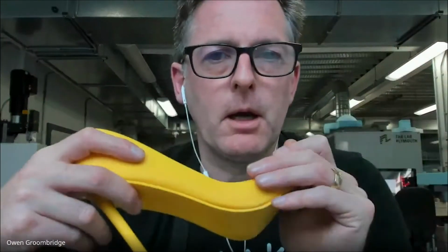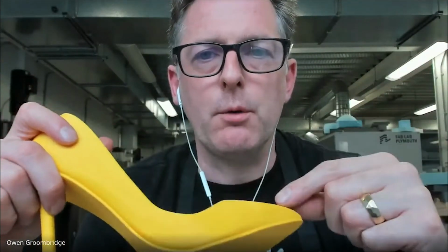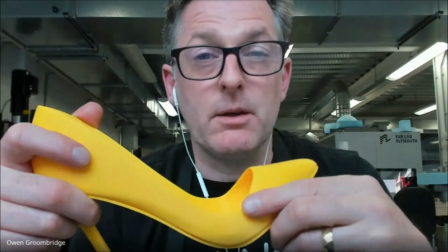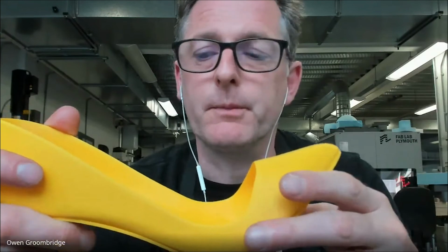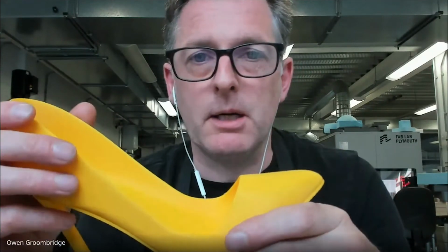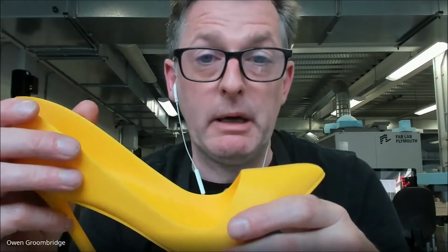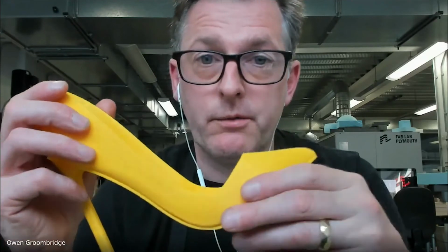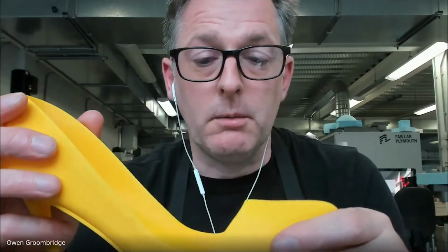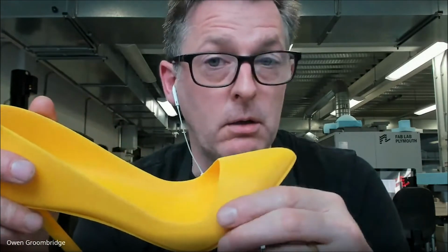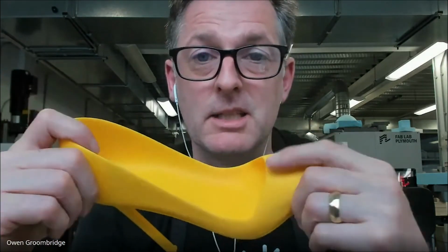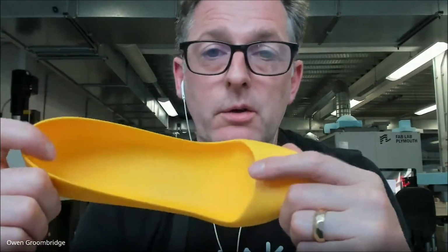Now the main con of these things is the materials themselves. With this kind of stuff, PLA, polylactic acid, is a bioplastic. It's made of starch-based material, so it's vegetable-based. How it's made is that they basically brew beer out of maize, with no hops. You don't drink it, and that beer is then distilled into pure alcohol, and then they catalyze it using something called tin oxalate.